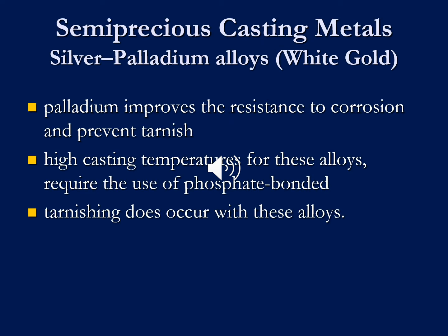Semi-precious casting metals, such as silver palladium alloys, which is known as white gold. Palladium improves the resistance to corrosion and prevents tarnish. High casting temperatures for these alloys require the use of phosphate bonded investment. Tarnishing does occur with these alloys.